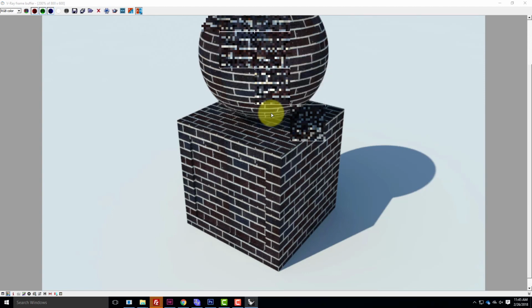And so what I'm asking you to do in this part 2a is to go find some of these materials, I'd say at least 4, and see how you can put them together. So I was successfully able to put this particular one together, and it's now rendering in V-Ray, which is good. Once I have it put together, it also looks like, in this particular case, they didn't tile the textures correctly because I'm getting some really strong seams. So it's a little disappointing. I'll pick another one and try it.